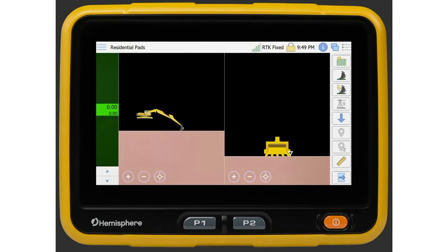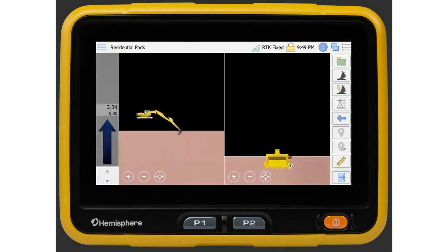First, place the bucket down on an area that you can reach again after you have tracked the machine back, and select the traverse icon. Notice that the icon has changed and the traversing text in the upper left. This is telling us that it's safe to move.